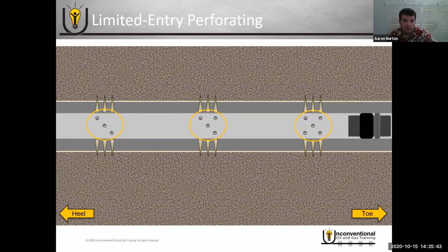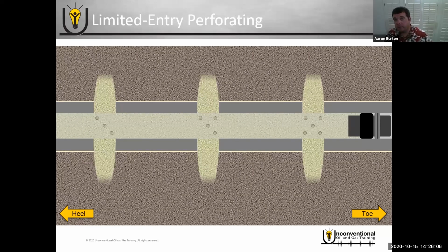And the heel-most perforation has 3 perforations in it. So now that's a path of most resistance from a flow area standpoint. The idea is you want to balance out how much energy it takes for the fluid to exit each set of perforations. And hopefully, if you do it correctly anyway, then you get your even fluid distribution back through your clusters.